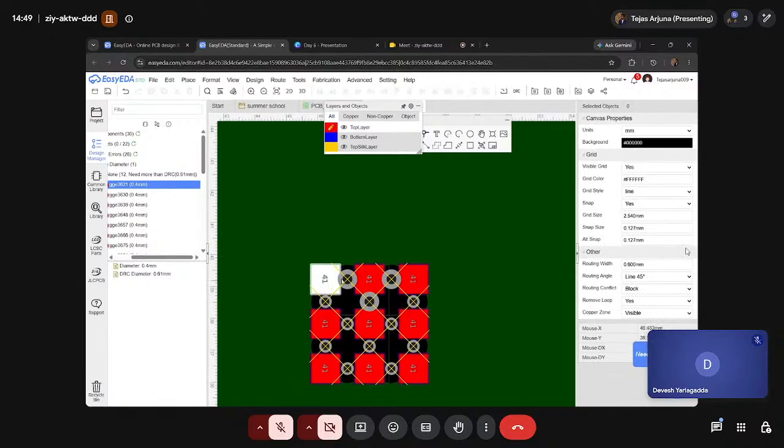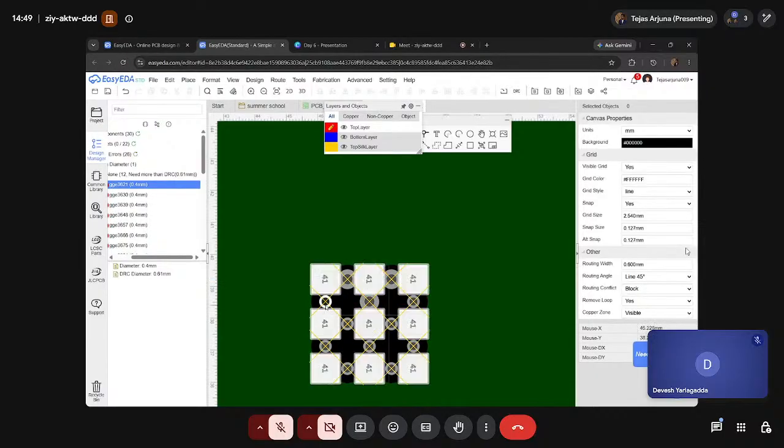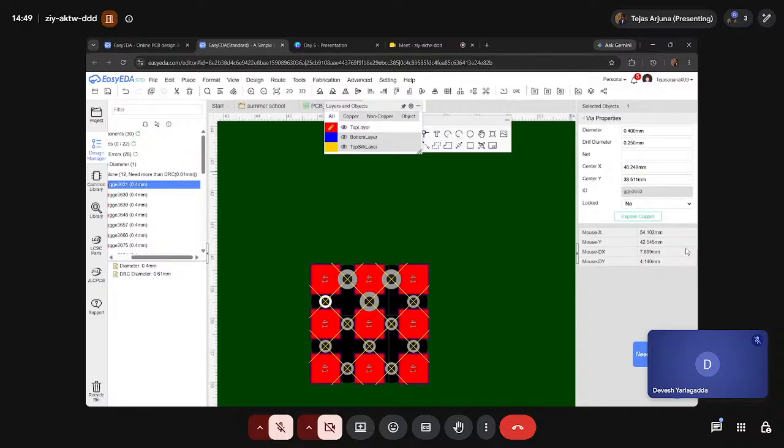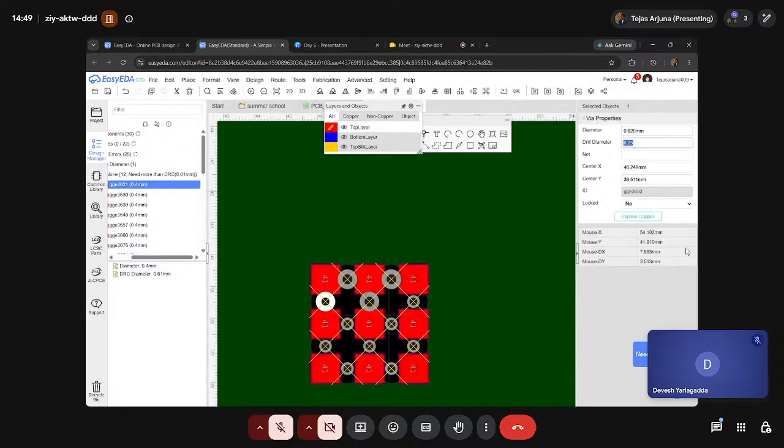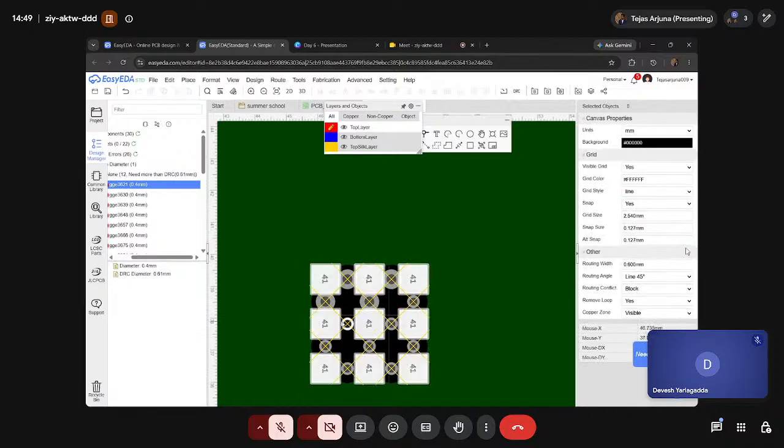Okay, you see, the pad and the PCB wires are making contact, but it won't raise an error. Why, can anyone say? Okay, no one. It is because both the wires and the pads have the same net. Means they are already in physical contact with each other. That is already made. Whether it is overlapping or not doesn't matter at all. It will not raise an error because both are connected to the same net, that is ground.